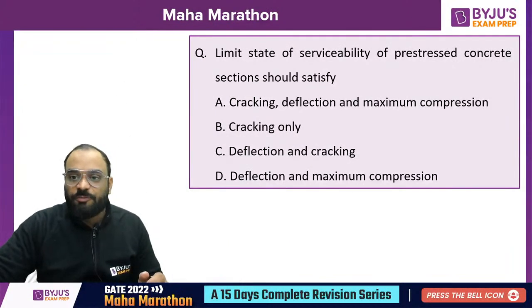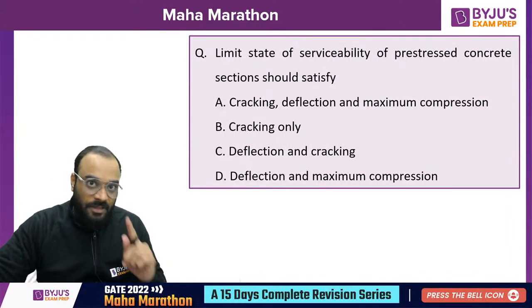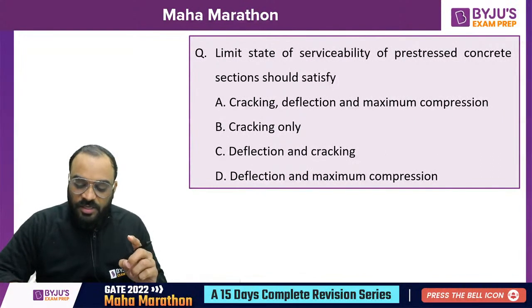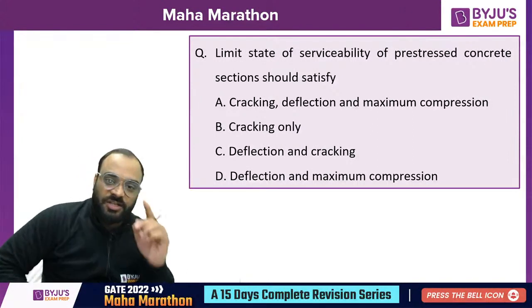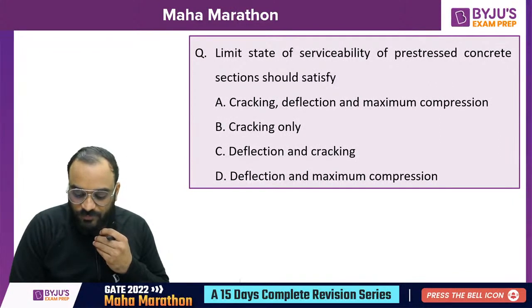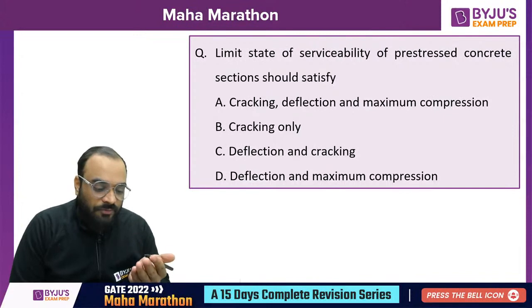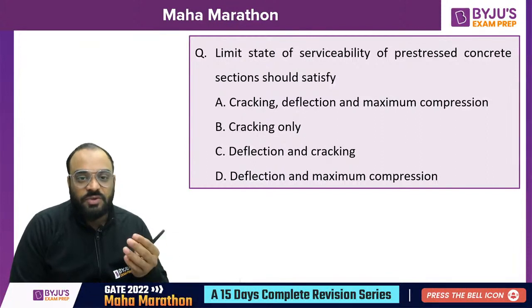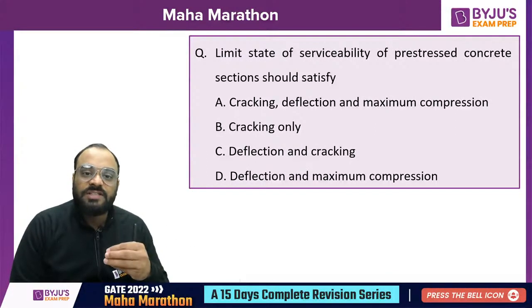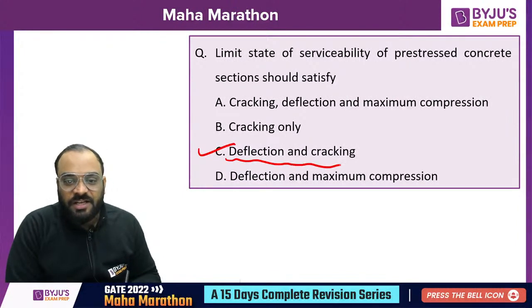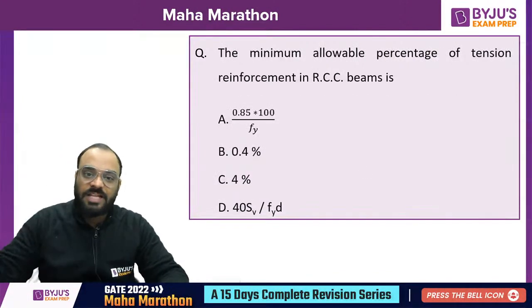Limit state of serviceability of pre-stressed concrete section should satisfy what? Please be careful. Guys, serviceability means the problem which may occur during the service. When we put the load during the service duration, whatever problem you are facing, you need to consider in the limit state of serviceability. Yes, it should be deflection and cracking. Deflection and cracking. Next question.